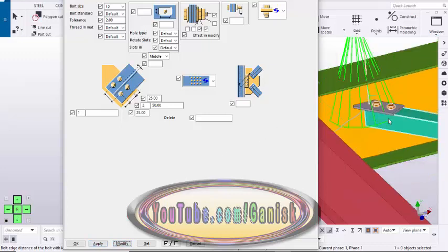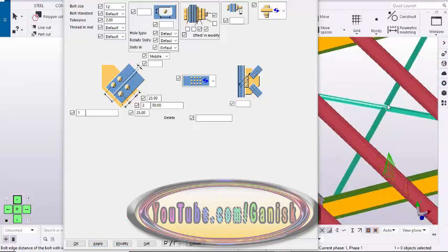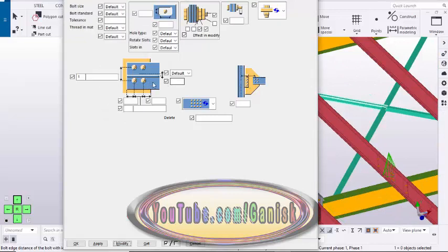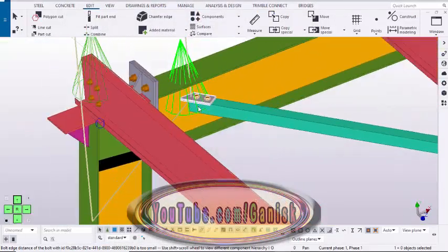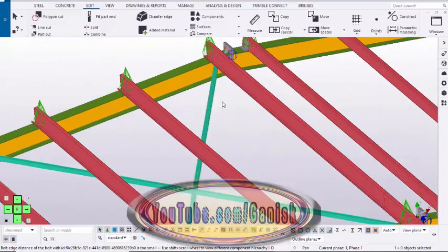Okay, before that we can directly enter this option also at this location. Go to the brace bolt 1 and do the same thing, otherwise just apply. Okay, now we're going to change the options at this location later. So we applied this connection property, so go to application components.